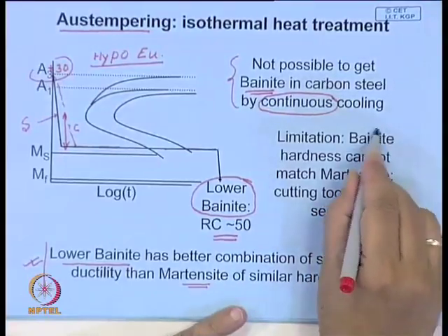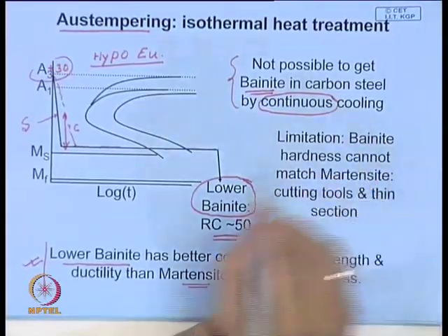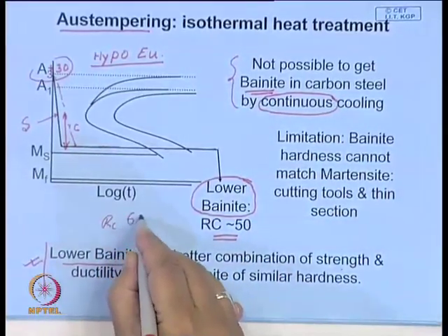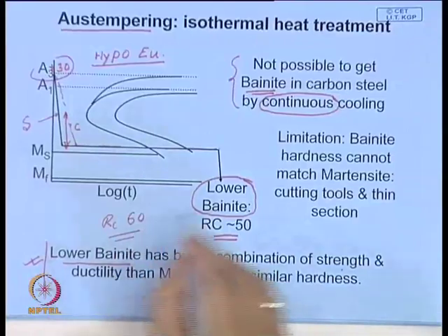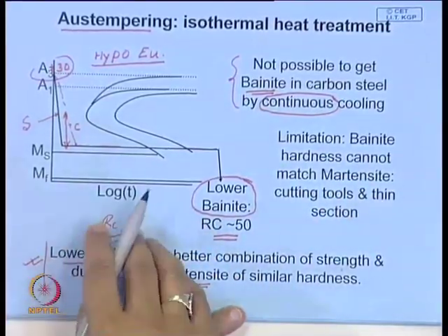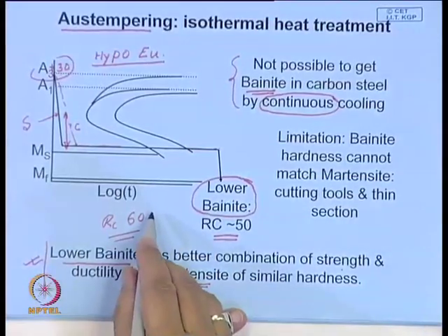One limitation is that in bainite, you cannot get a hardness of the order of, let us say, RC around 60, which is needed for cutting tools. So, the hardness cannot be matched. For that kind of application it may not be suitable.